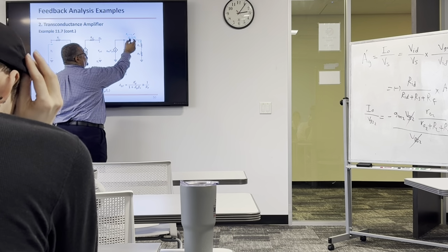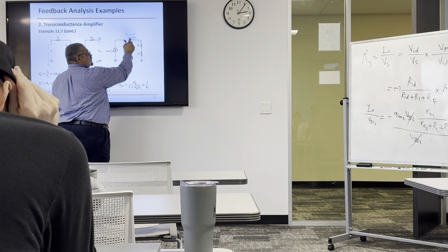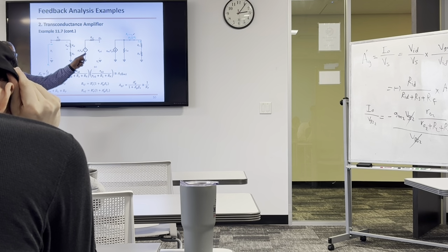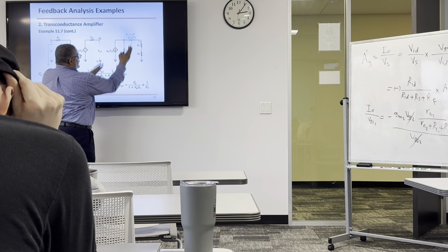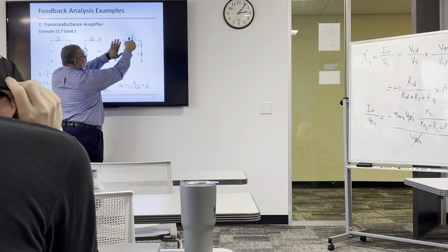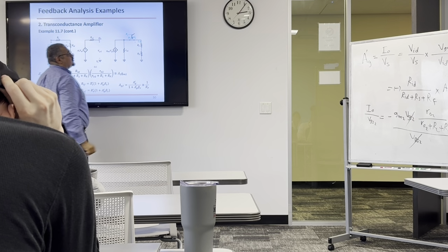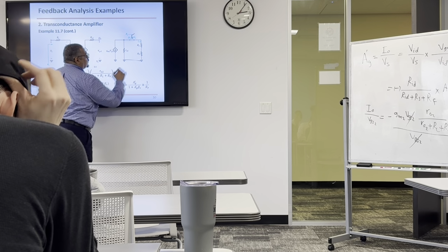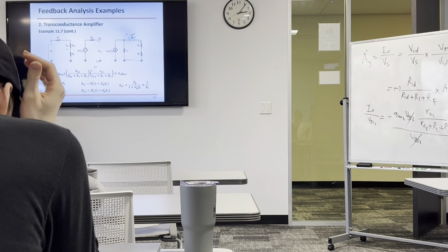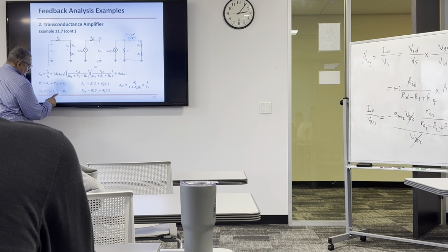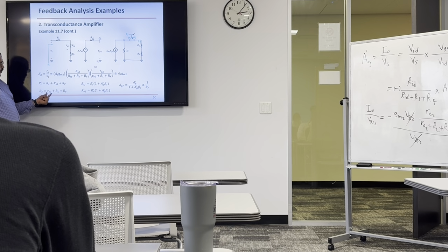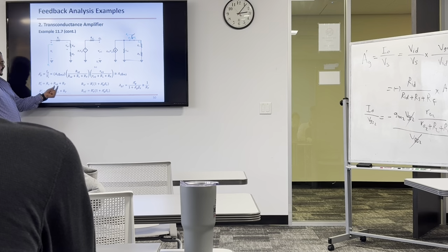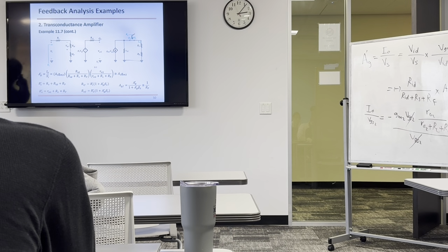Similar to if you connect the current source and you measure the voltage divided by the current here after you cut. So if you cut here and you assume this one open, and you cut here and look into the impedance from here, what do you see? The three are in series, right? So it's RO2 plus RL plus RS, okay? And this simplifies to just RO2. This simplifies to just R input differential, okay?